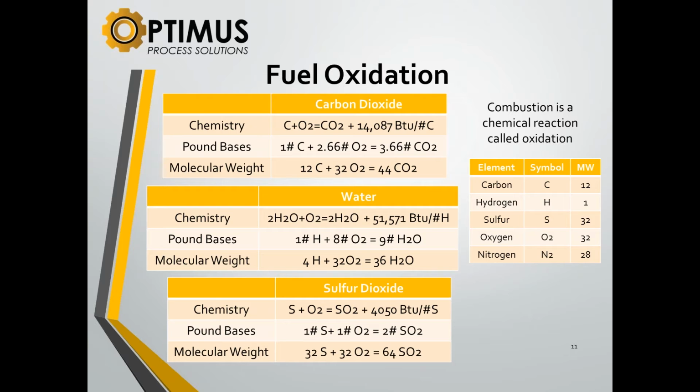There are some other factors in here: coal isn't 100% coal. It can have shale in it. It can have moisture in it, or other things, silica rock. So a pound of coal isn't a pound of carbon. So you put in a bucket from the pile, there may be a lot of other things in there that you won't burn. So you really want to get the chemical composition from your shipment. Yeah, you might be heating up rock. Okay.